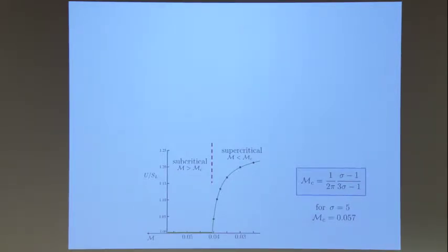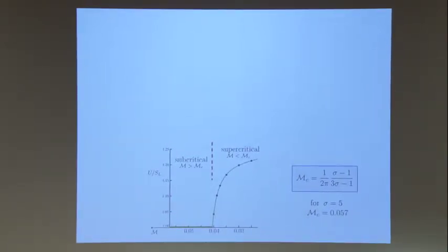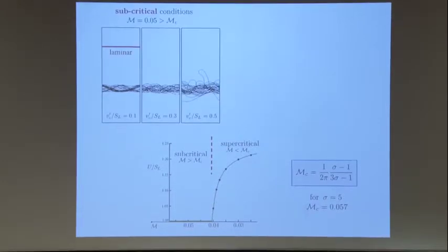just to remind you, this picture was the bifurcation picture in laminar condition. It was for the larger Markstein number, the flame was stable, and when you reduce the Markstein number below a critical value, you obtain these cusp shapes, and they propagate at a velocity higher than the stable flame. The green curve is only the stable flame under this Markstein number. And this is the critical value in case it comes about.